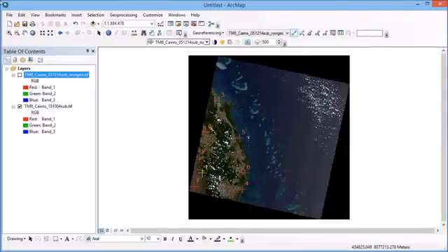So now I've moved on to create a number of ground control points across my image. So you can see that what I've tried to do is to spread those out across the image as much as possible. And rather than having a cluster of them in one small area, for example, which would mean that my transformation might be good in that area, but across other areas of the image it may not be very good at all. So I've spread them out to try and help that transformation work for me.